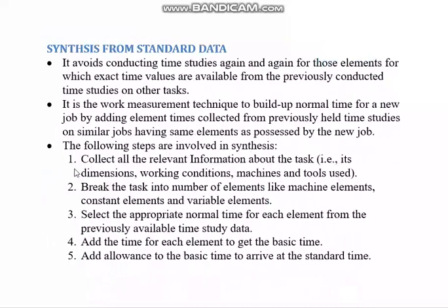See, now here a definition is given for synthesis from standard data. It is a work measurement technique to build up normal time for a new job. See, normal time and basic time are the same thing. Here also we are estimating basic time only. Basic time means thereby standard time. Apart from that second thing, all the other work measurement techniques are estimating the standard times. They are estimating the normal time and thereby the standard time for a new job.